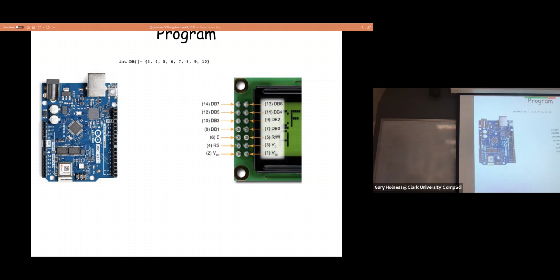And so when you want to wire it, and I recommend that you use the wiring in the example so that you use the example code quite readily, you're mapping from a digital I/O line to a signal pin. And so here, the choice of DB is to mimic the DBs describing the data bus for the signal lines on the device.